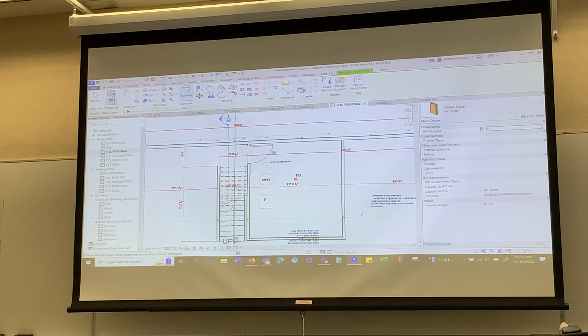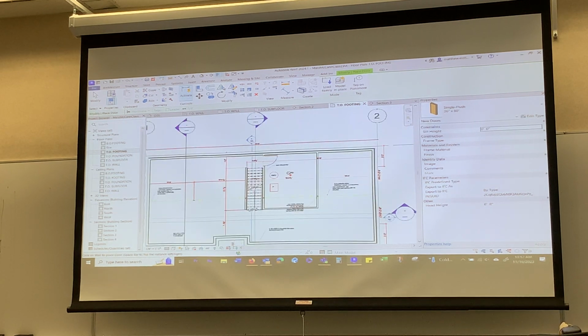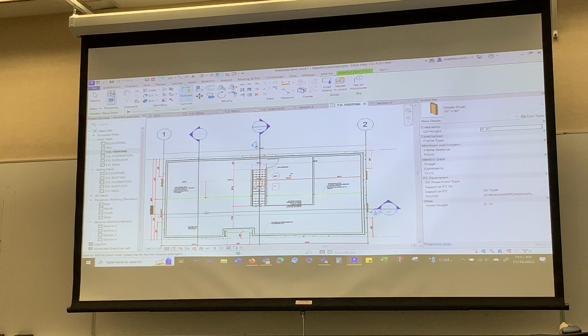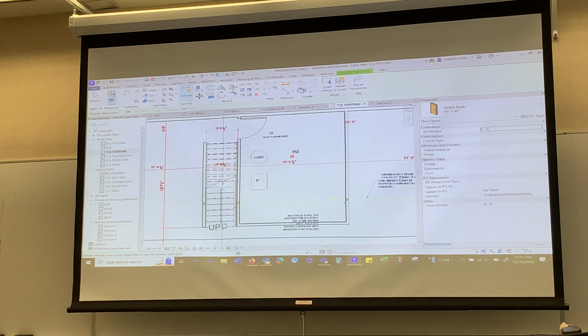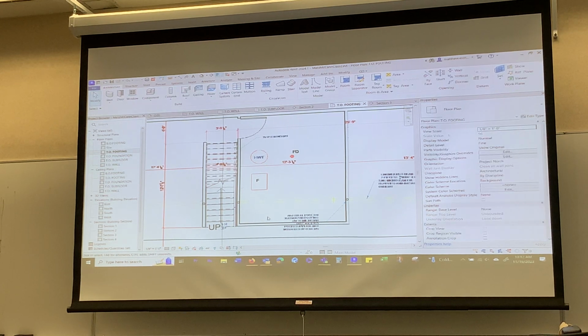It can swing in. You need a 36-inch door in a mechanical room by code, so you should put a 36-inch door there. This isn't in the DWG files, I'm just winging it. You can do the whole basement development if you want to, but I'm not going to mark it. All I want you to do for the assignment is give me a mechanical room. It's your choice, whatever makes sense. Then go find a hot water tank, maybe a furnace. That's enough. You can put a boiler in if you want to, whatever, just put some stuff in here to complete the check mark on the assignment.